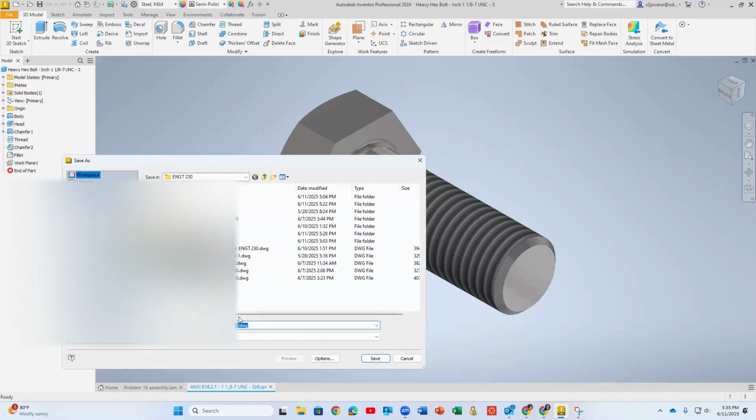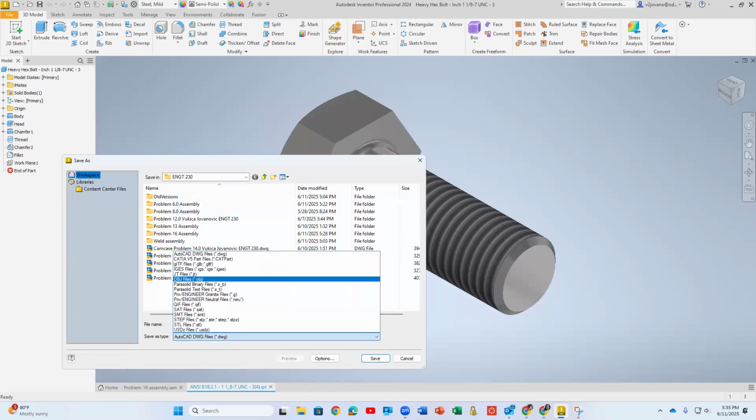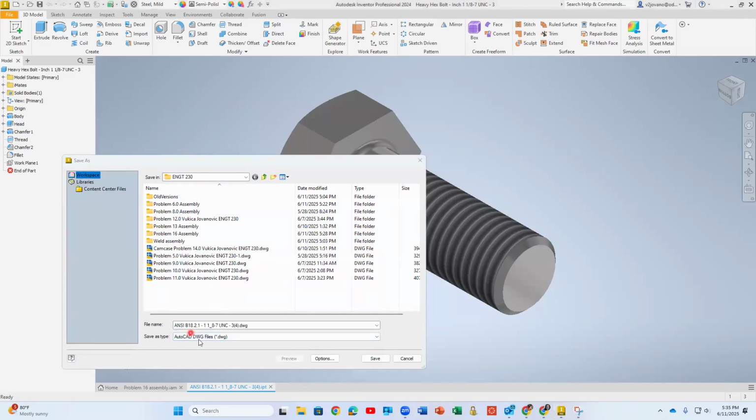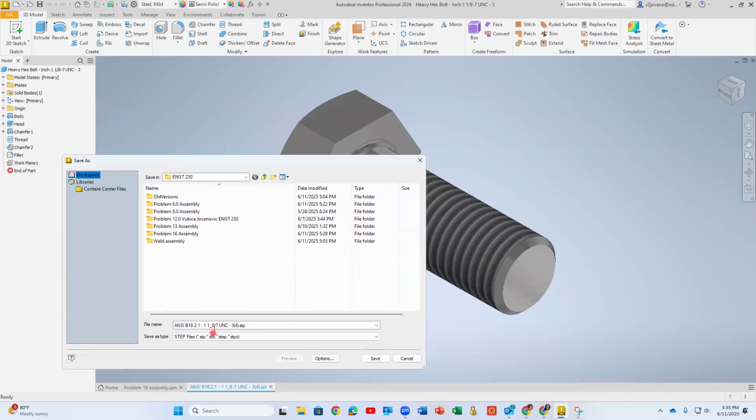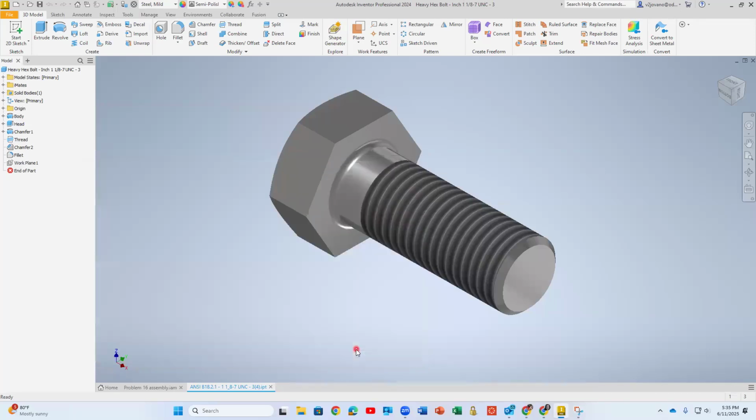And then for all the parts you create in Inventor, you always have the option to go to export CAD format, and you can switch from the generic Inventor file, and you can also make a STEP file or an IGES file. So for example, if I'm exporting this as STEP, you can get this into any other CAD software. So parts you made in one software, you can always import in another.